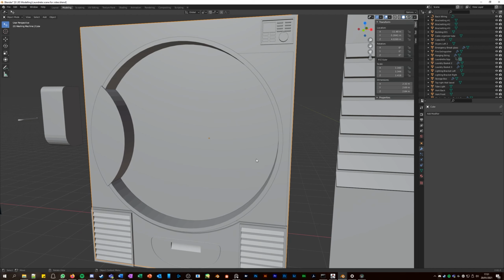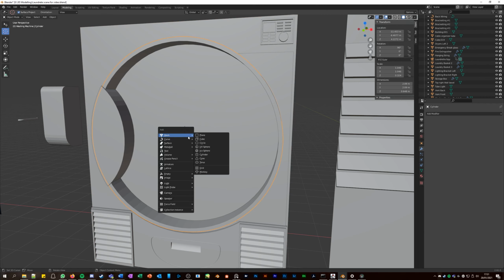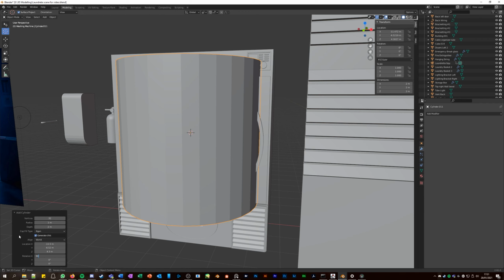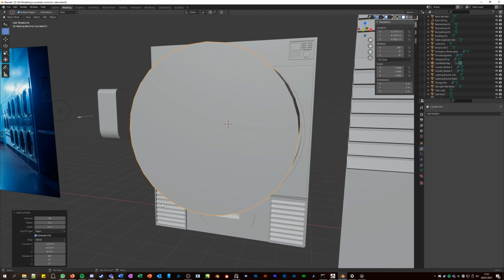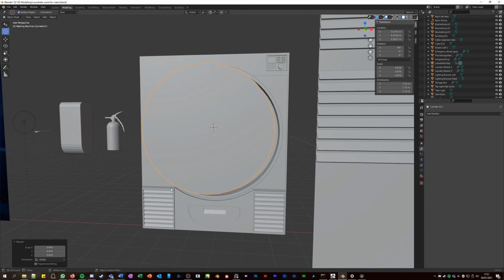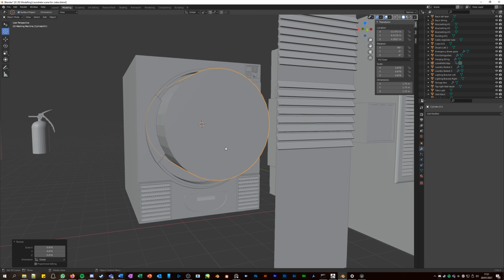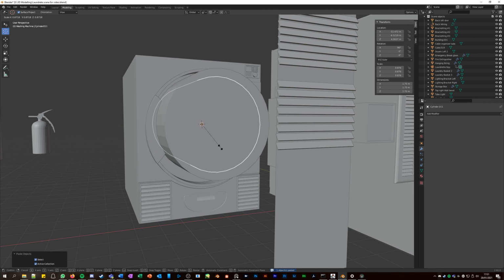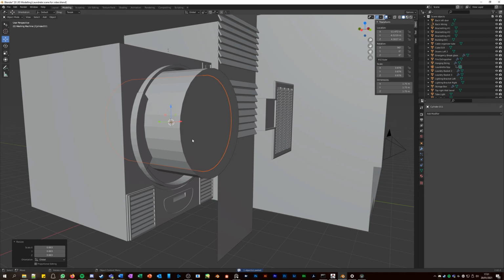And then to create this metal rim, I took this outer circle, I started with a cylinder, rotated 90 degrees around the x-axis, so it sticks out. Scaled it down a bit. And then I took another cylinder, so if I duplicate that, and scale that down inside of it, pull it out of it, and use the Boolean modifier I talked about before.